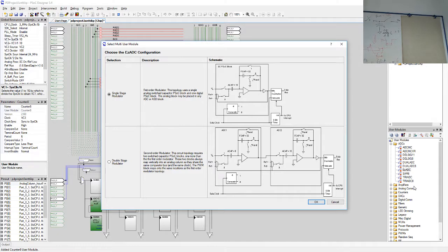By software you can connect this band gap input right here and fix 1 point. Do a 1 point calibration anytime. You can also do 2 point calibration by, let's see. Yes, of course, you can set the gain, for example, at 0.5, and then you have 2 points where you can do the calibration.